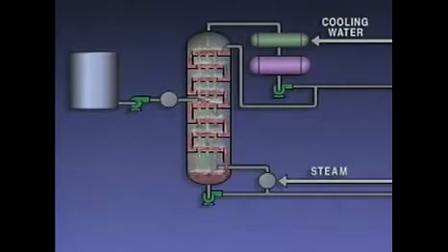The reboiler provides the major portion of the heat that's required to make the distillation process work. In the type of system we've been discussing, the heat supplied by preheating the feed is not sufficient for proper distillation. The reboiler is needed to provide enough additional heat to vaporize the lighter fractions in the tower so that the products meet specifications. Although all